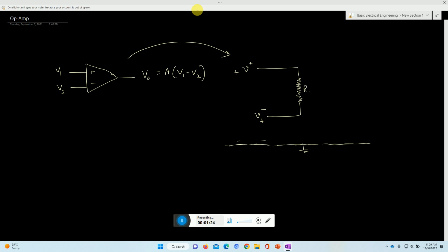And this resistance is called Ri, which is assumed to be very high, and this terminal is plus and minus. The potential across the plus and minus terminals is VE. On the output side there is an R0, a resistance which is very low, and there is a dependent voltage source which is also connected to the ground over here. This dependent voltage source will be called A into VE, A times the voltage across this Ri, and the output terminal will be called V0, which is the potential of this node with respect to ground. So this is all it is about.